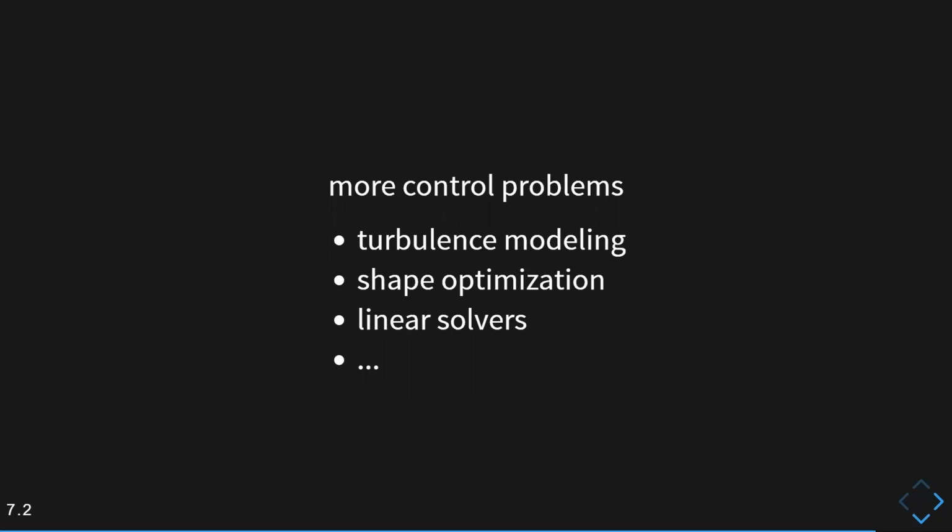And of course, when you think about linear solvers, we have a lot of degrees of freedom when you look at the multigrid solver, for example. Typically we would set those parameters at the beginning, hope that they are okay-ish, and then just let them run. But when you have a transient simulation, it intuitively makes sense that the solver settings that are optimal in the initial transient state are not necessarily optimal when you reach a quasi-steady state. So setting the parameters in your simulation can also be considered control. And of course, there's also been work on shape optimization. It's just the same.